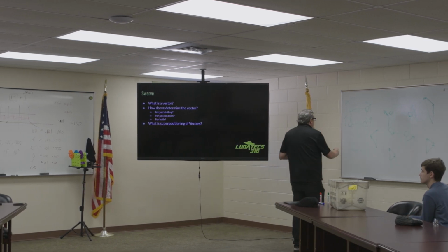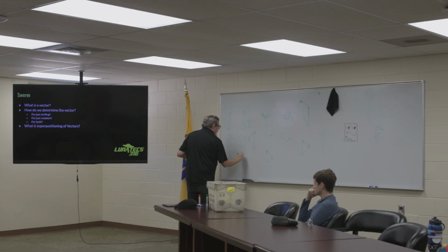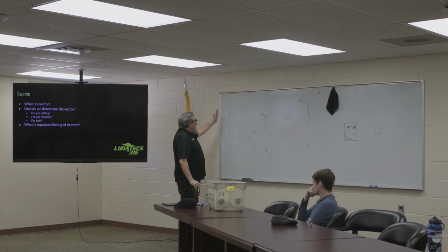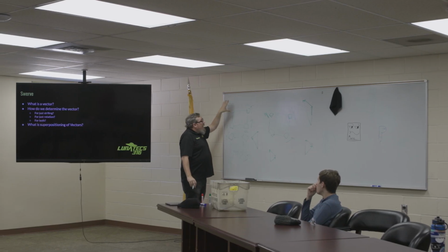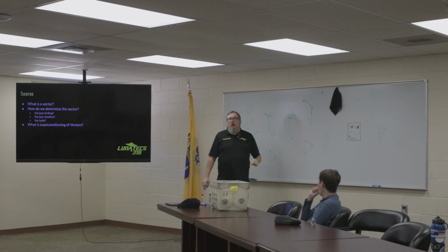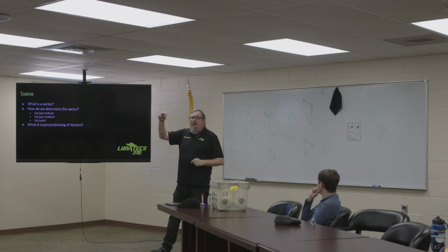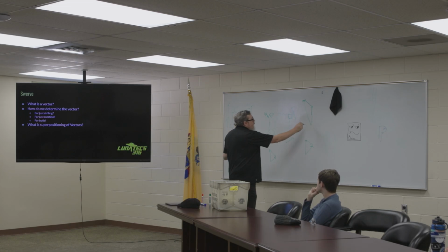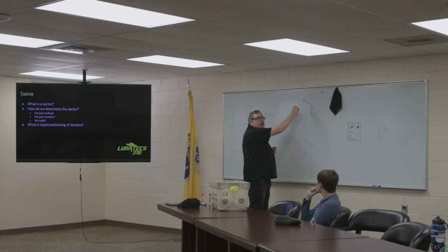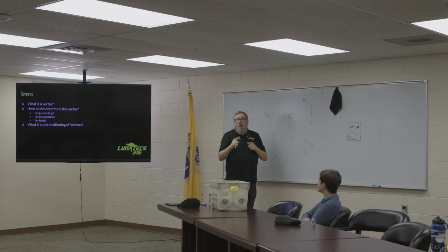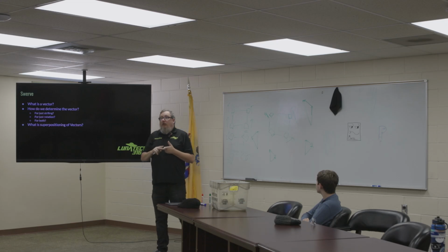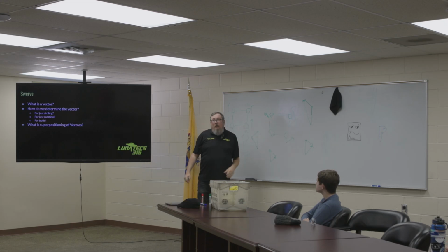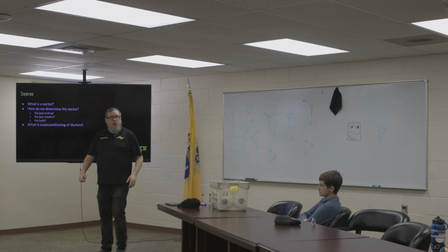So, if I'm looking at rotating and I got power on wheels like this, and I want to also send power to this, I can put these vectors together. It's called head to tail vector superpositioning, where you connect your two vectors and then you draw a new vector that represents a new magnitude with a new position, with a new angle. And then we can calculate that on here, and that allows us literally to go downfield while spinning.